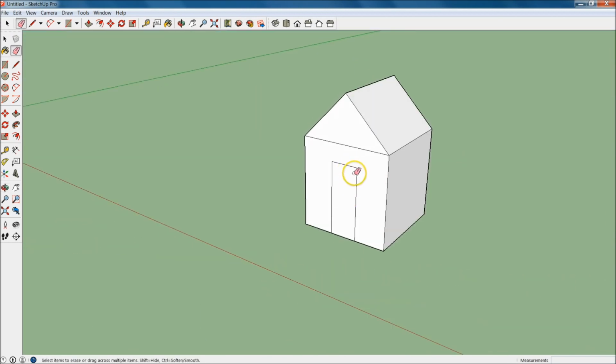And now you're thinking to yourself, okay, I think I made this door a little too high. I actually want it to be 7.5 feet. So what we're going to do now is we're going to use the move tool. If we go right over to here, you'll see these 4 arrows right here. Go ahead and click that. That's your move tool. And then we're going to hover over this line right here, and we're going to drag this down, make sure it's on the blue plane, the Z plane, and then we're going to drop it. And after we've already let go of it, that's when we're going to type in the 6 inches. Now again, we can do 0.5, or we can just type in 6 and hit enter.